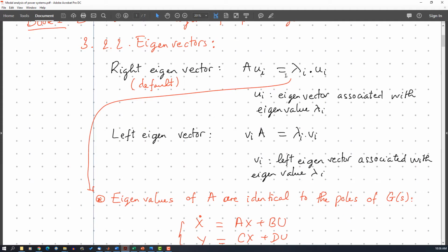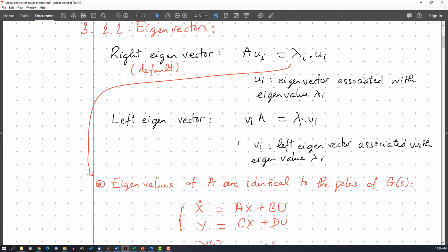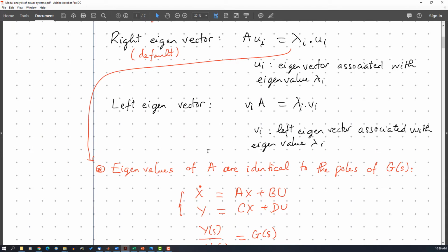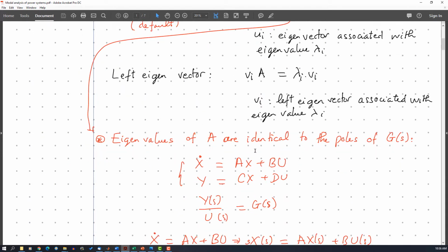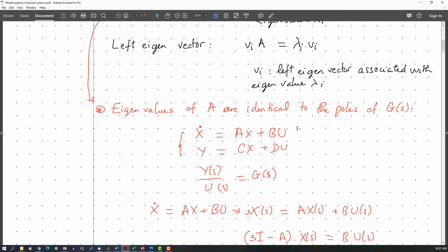And from this, the first thing you have to do is form your system into the state space form like this, and it should be linear. So first you have to linearize your system and put it into the state space like this.